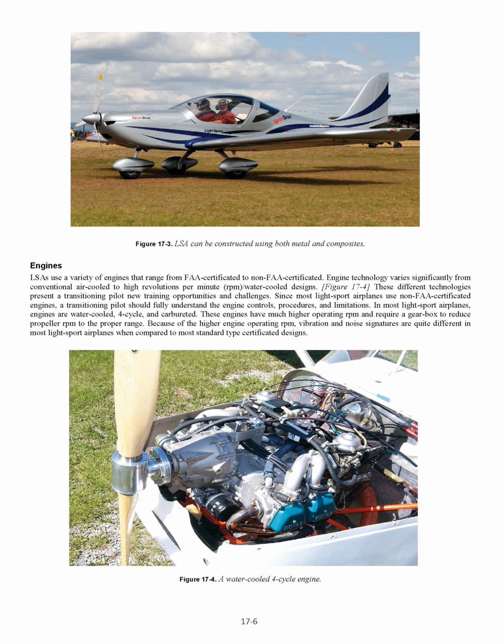In most light sport airplanes, engines are water-cooled, 4-cycle, and carbureted. These engines have much higher operating RPM and require a gearbox to reduce propeller RPM to the proper range. Because of the higher engine operating RPM, vibration and noise signatures are quite different in most light sport airplanes when compared to most standard type certificated designs.